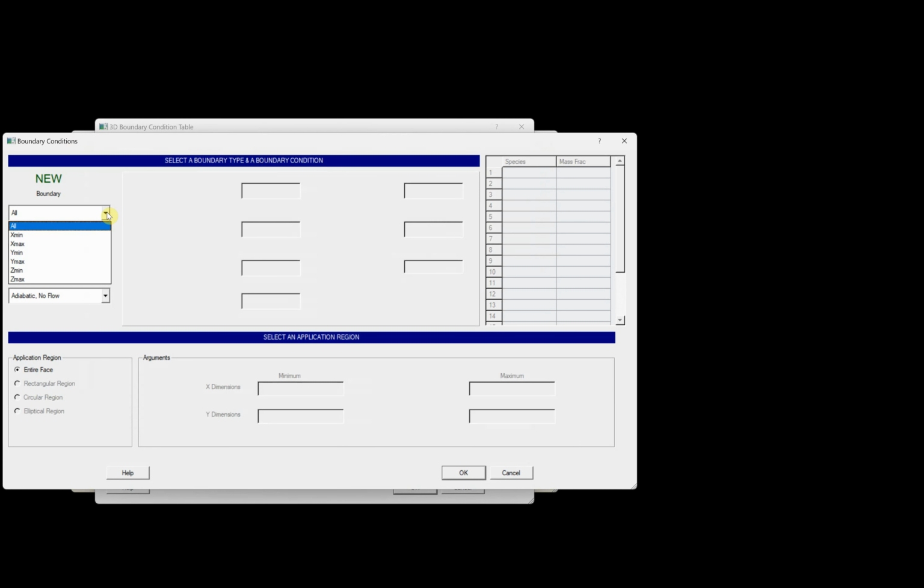Okay, now this overwrote the normal velocities of all these other momentum boundary conditions for the wind, but it did not overwrite the crosswind velocity. And that's why we wanted to do it in this order. However, it did overwrite the normal condition for the inflowing wind. So now we want to apply the wind again, but only on the y max boundary.